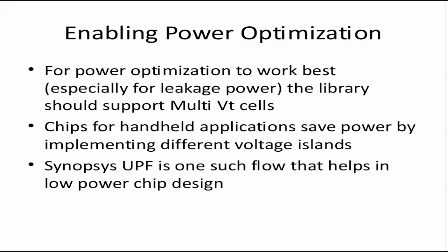How do we enable power optimization? For power optimization to work best, the library should support multi-VT cells, especially for leakage power.